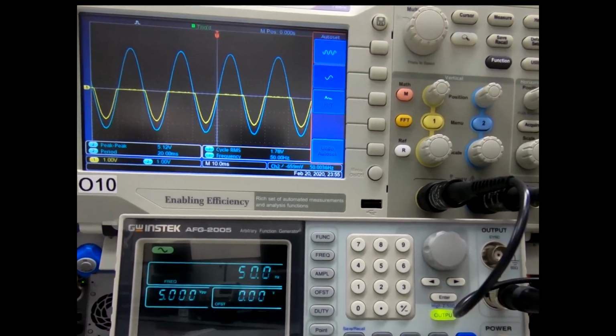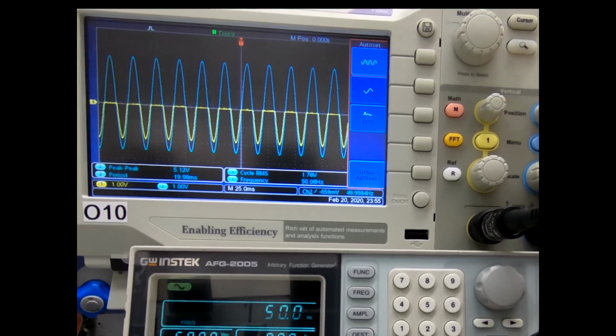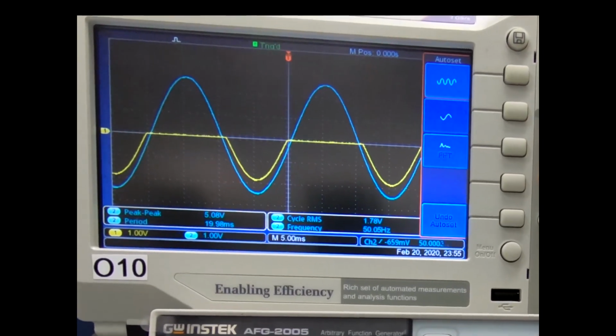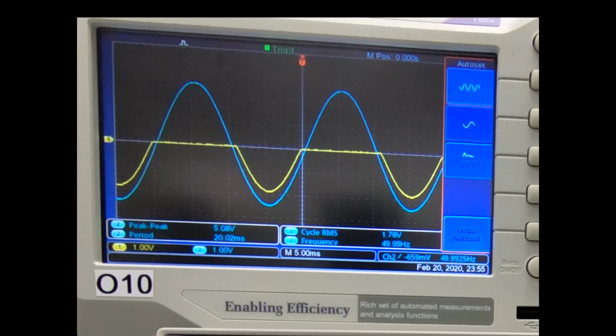And once more we see the blue input waveform is the sine wave, and the yellow output waveform is some of that sine wave. This time we see only the negative half cycles are getting through, and even they are clipped, which you can analyze using your diode theory to give some good interpretations of why that might be. Okay, thanks.